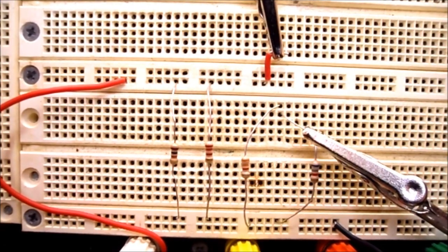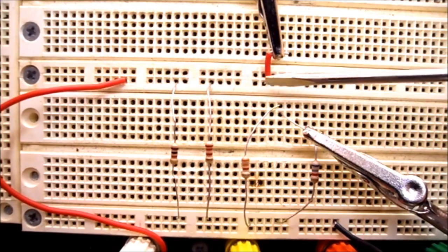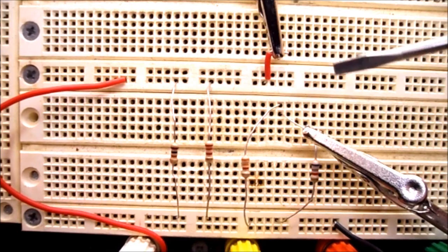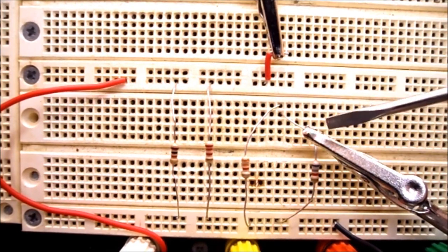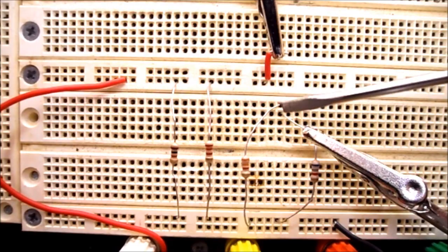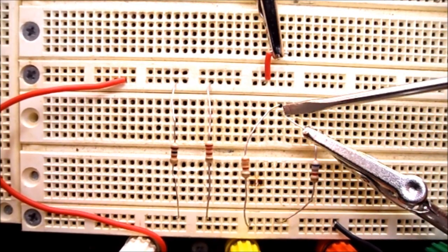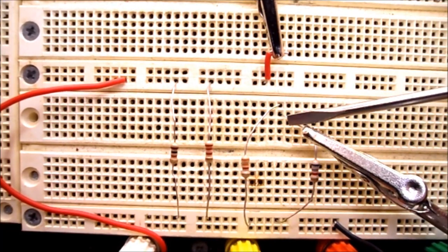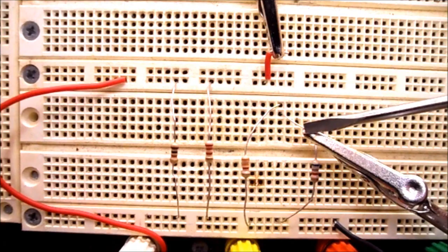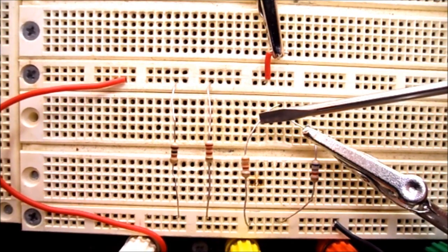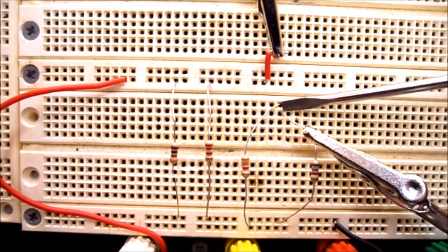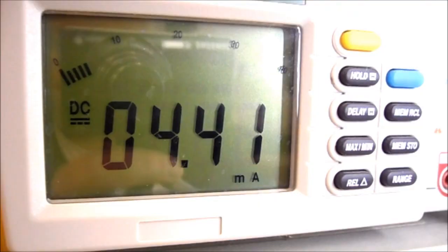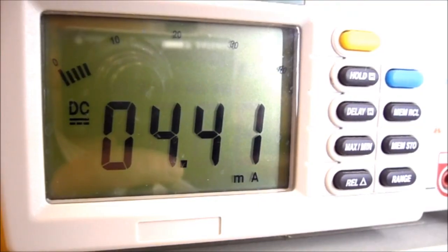Now the ammeter is coming in and going to where I took those 2 resistors out of. And the black lead for the ammeter is just clipped onto one of those resistor legs. Because both legs are joined together in the same little bus line, it means both legs are connected together. So I can put my alligator clip on R number 4 or R number 3, it doesn't matter, because they're both connected together in that same little bus line. So my current reading is 4.41 milliamps.